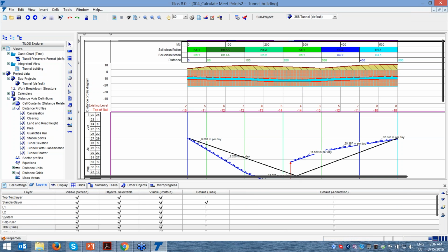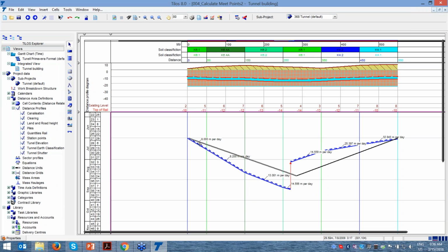You can see that soil type impacted performance. And here you can see that, okay, they are meeting at 275 meters. But this is not really what we wanted. I mean, TBM1 started and came to the point at 275. Do we really want TBM1 to wait till TBM2 comes, or would we like this TBM to continue? So that's why we stop this and wait here; instead of this, we may schedule it and estimate the real meeting point.